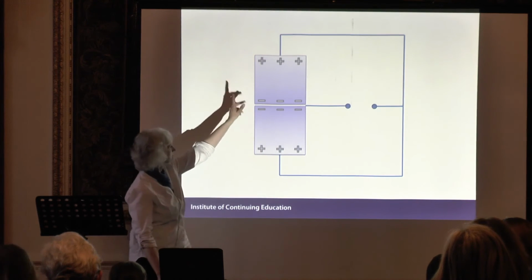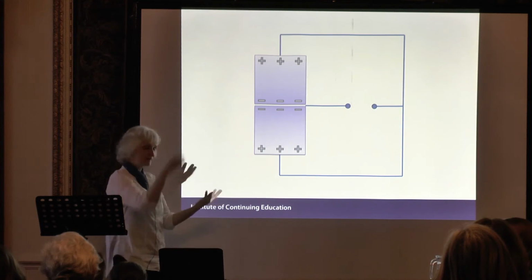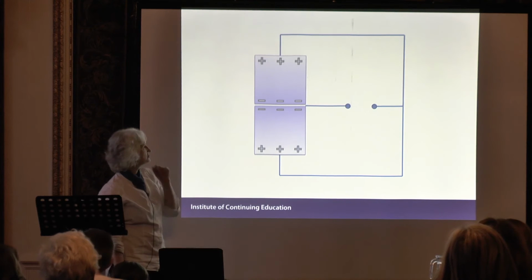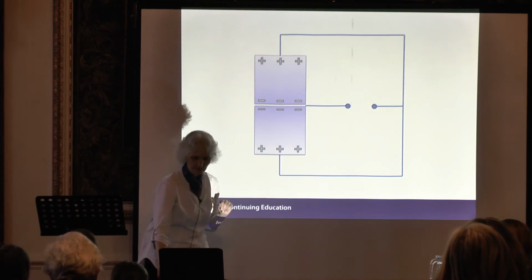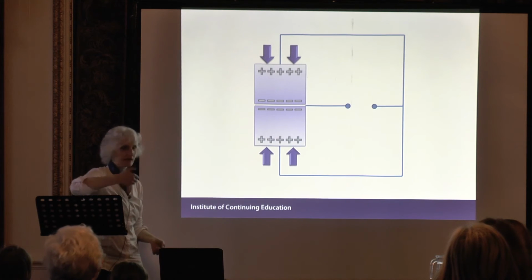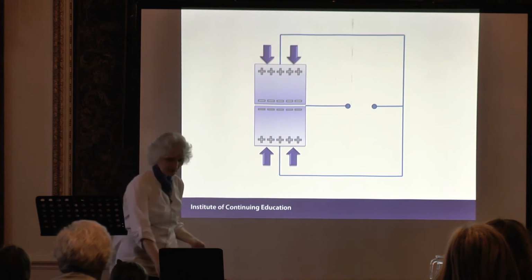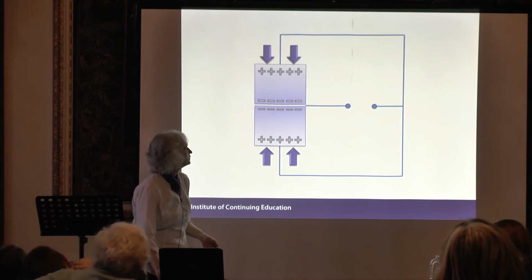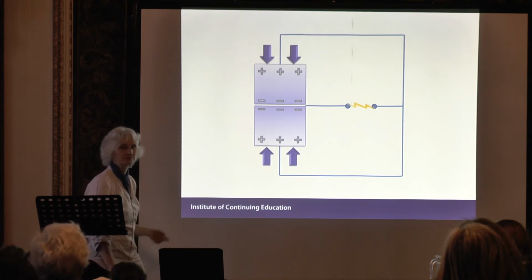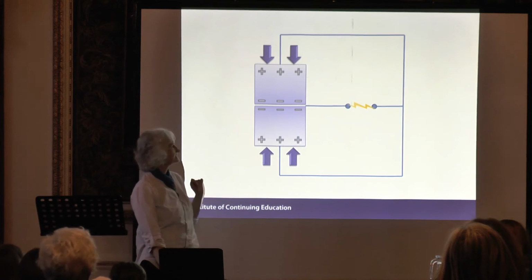So we have 2 bits of piezoelectric material, but they're face to face now. So they have their negative charges facing each other. And we come along and we squeeze it. That's what the clicky bit on the gas lighter does. So we apply force to it, it gets a bit smaller, and then it discharges across the gap. Makes our spark, and it lights the lighter.